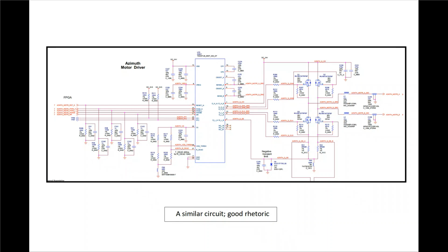The symbol is also made sufficiently large, and its I/O pins are spread out to allow placement of the surrounding passive components in a clear and meaningful fashion. Pull-ups go up, pull-downs and the bypasses go down. The high current paths through the H-bridge and then off the page are readily apparent. The gate control paths are easily traced, and the function of the associated passives is readily understood.